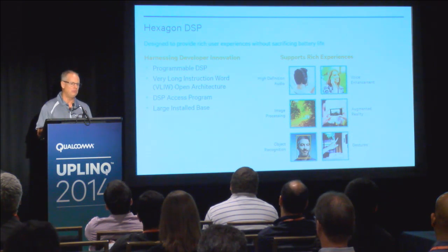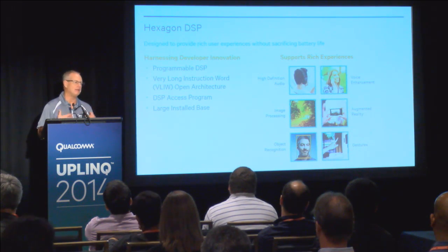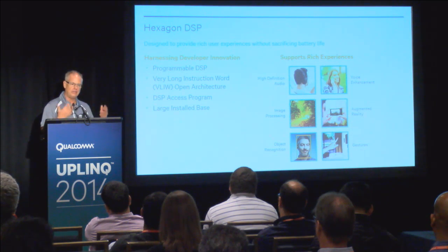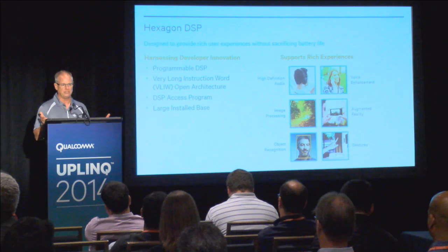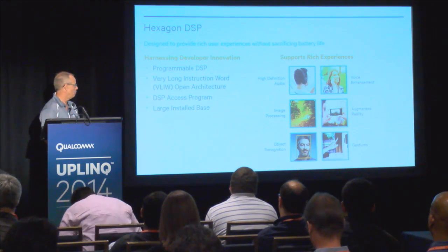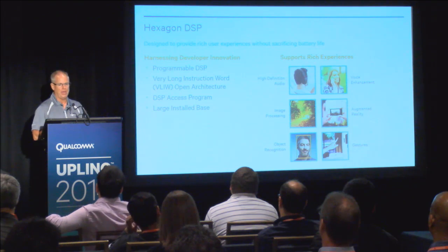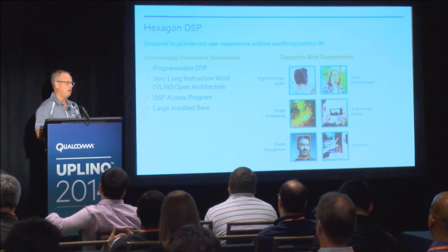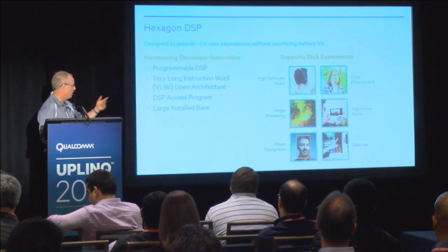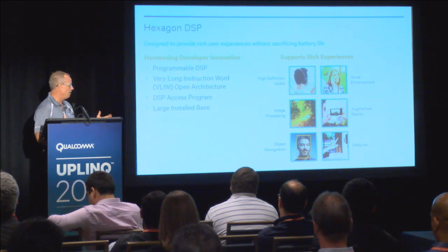When you get to the GPU, you think of quarters of a watt of power. So we shut off the GPU, we shut off the display, we shut off the CPU, and you're playing music in the background in the DSP at the tens of milliwatt level. I think our MP3 decoder is about 2 milliwatts of power, but when we add up the rest of the circuitry to support that, you get that kind of performance. Now, since we have the DSP, it's been dedicated for audio and speech functions. We also incorporate other use cases like image processing, augmented reality, object recognition, and gestures.